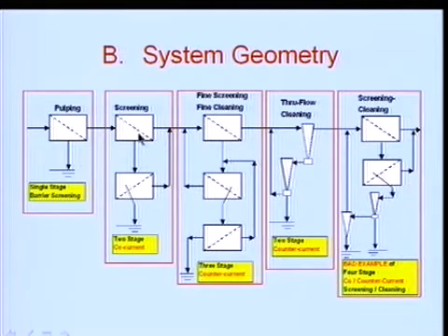So, here are some examples of stages in the module. First, pulping generally is single stage. Here is a screening module, co-current, where the accepts of the screen are going forward, 2-stage system, 3-stage system, cascade type or counter current, because the accepts are going backward to its preceding stage. Here's a two-stage reverse cleaning system, counterflow or cascade.